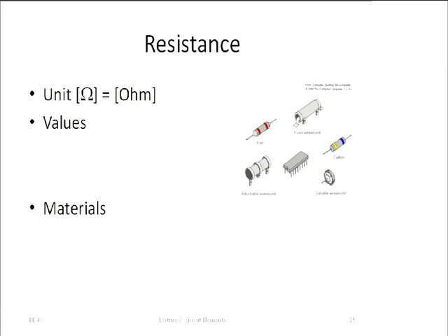And what's the resistance of that thing? Well, a few hundred megohm. Okay? So getting a resistor that has much higher values is kind of difficult. You have to wear gloves if you solder it or so. Okay? But we're not going to use those. It's just in practice hard to make resistances that are much, much larger than maybe 100 megohm.